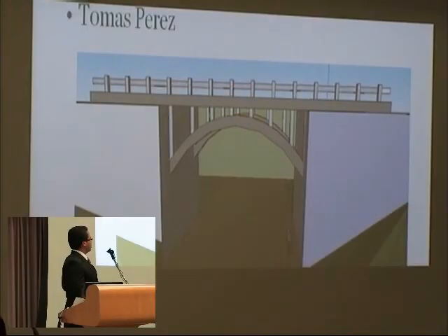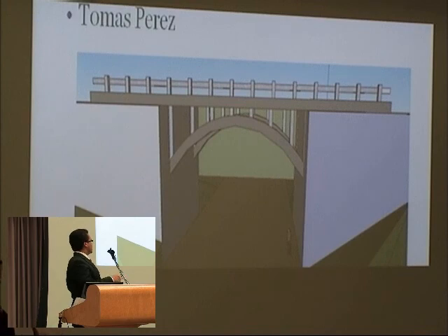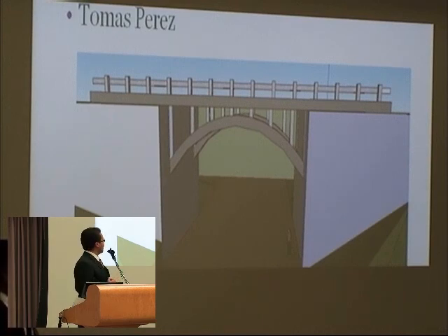To start, our client asked us to design a bridge. The reason for this was because right under the road that provides access to our site, we have a Rhode Island DOT right-of-way, which we actually had to make sure that whatever structure we built there complied with the clearance requirements for a possible railroad that they would have liked to include there. Once we found the clearance envelopes, we realized that they were curved, and actually this served as an inspiration to the design of our bridge.